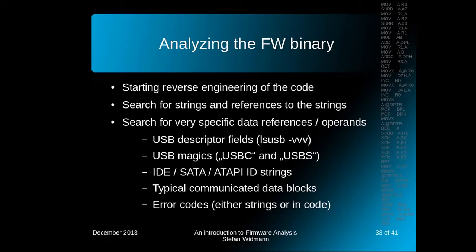Take a look for IDE, SATA, ATAPI ID strings saying I'm an OCZ SSD device, for example. Maybe when you've sniffed the communication with the device, you've already found out some typically communicated data blocks. You can try to find them. And last but not least, maybe your device provides some error codes, and you can either search for strings or for operands in the opcodes.